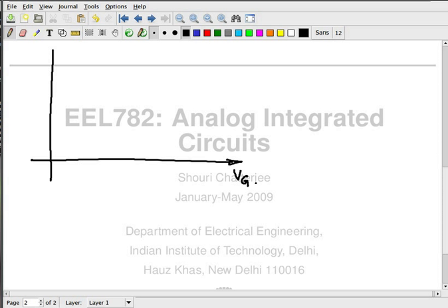I'm going to call this Vg. Charge and charge density, both, yes. Not on source to drain. The amount of charge only depends on the gate voltage. As I increase the gate voltage, the amount of charge in the channel increases. The profile changes. The density profile changes because of the source to drain voltage, nothing else.